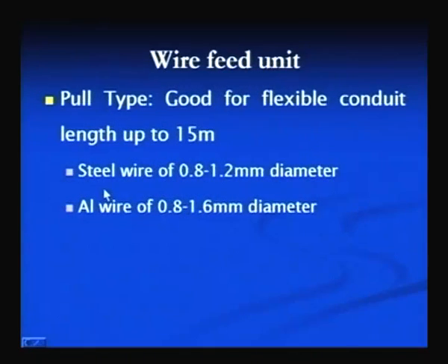So, to reduce fracture-related problems, particularly with aluminum wires, which normally get damaged due to rubbing against the conduit surface, a lining of nylon or other soft material is normally made in the conduit pipe through which these electrode wires are passed.